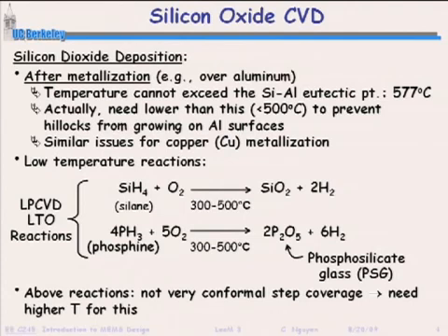So you're now talking about something where maybe you deposited the oxide over a structure like this. So that's your initial structure. And you deposited the oxide, so it's depositing at 400 degrees C or so, so that's not a conformal deposition. It may deposit like this over that structure. Okay, so it isn't conformal, and that leaves some topography.